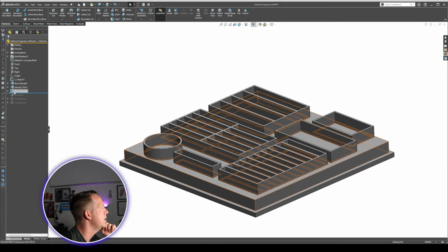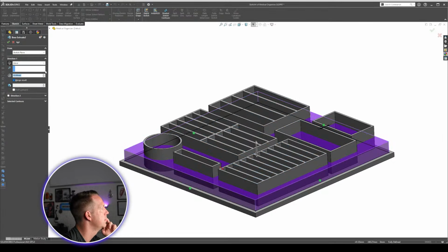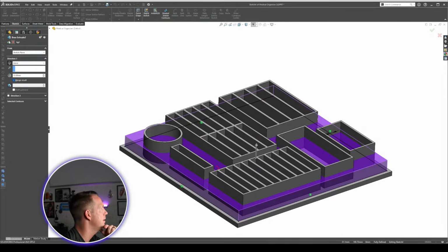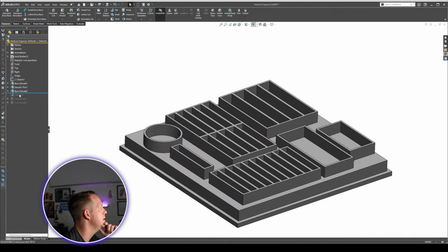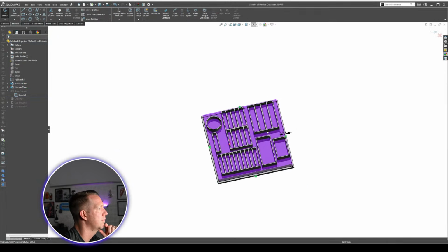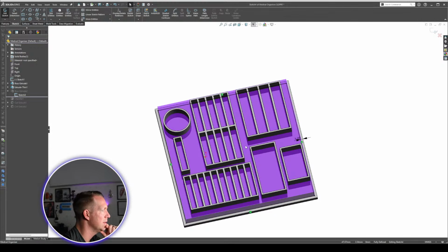Now I've done this boss extrude up, but this boss extrude that comes up, could I change that? Yeah, if I didn't want it to intersect with everything, that's a bit trickier. Probably what it needs to be is a different kind of sketch. Let me show you this trick. If I want to do everything on the outside, I'm going to go convert entities.